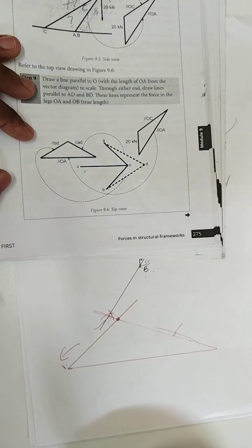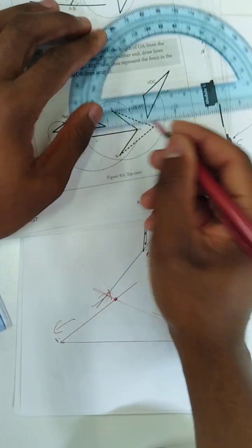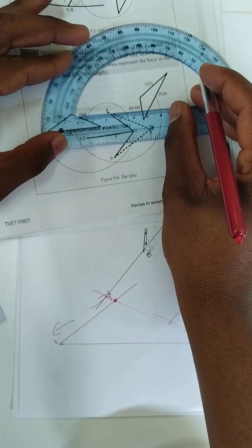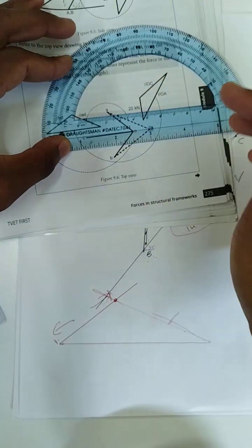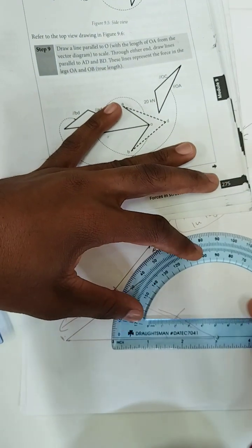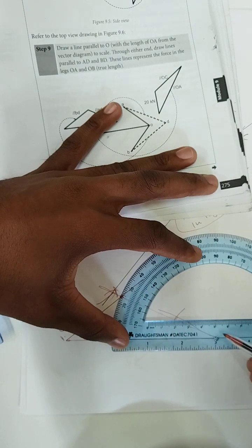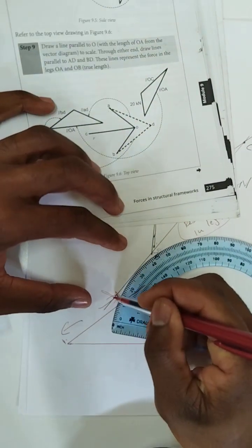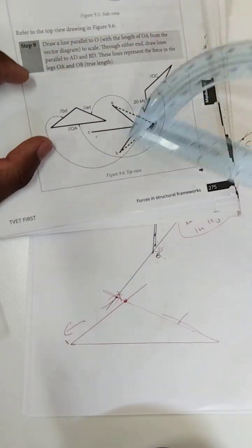So if you don't want to use this ruler method, you can still measure the angles. You can divide this thing into half like this and measure this angle here like that. So this angle will be about 30 degrees. Then you come here, measure 30 degrees, and then you mark it there. Remember, I'm just doing things rough here.